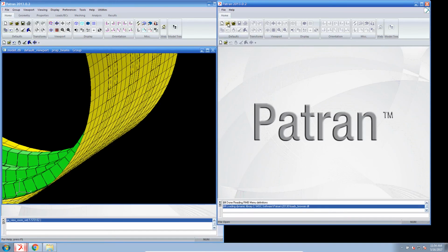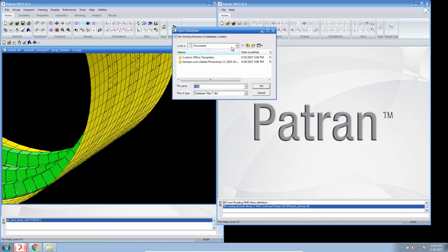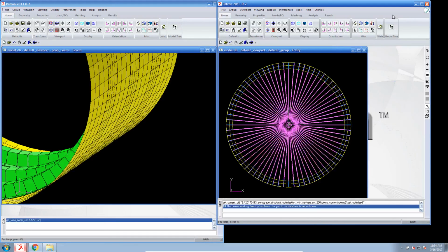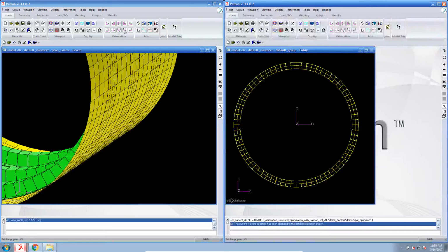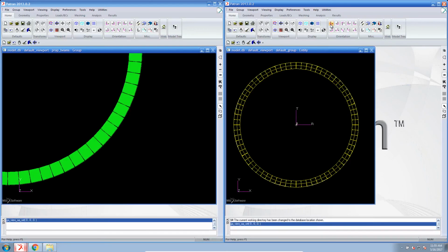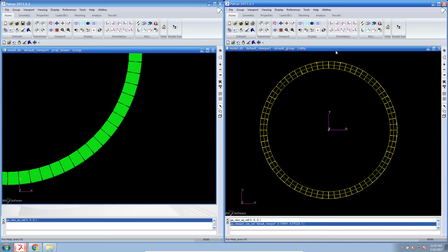And that's because I misconfigured the offset relationship in a previous example. So it's important, as I'm saying now, to always look at your results in your pre-post processor, verify the new dimensions, verify the offsets, and verify the new structural results just to make sure everything looks okay. So here on the right is what the new optimized model looks like.